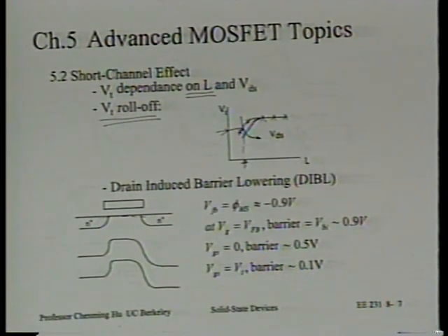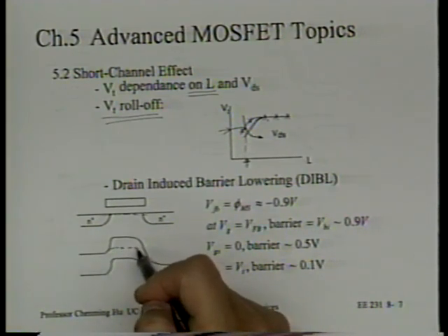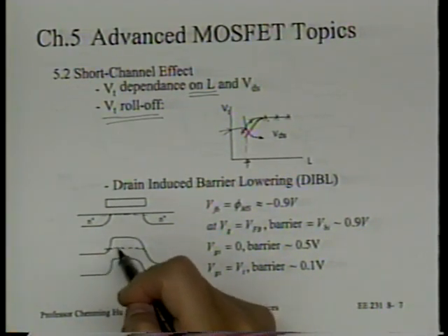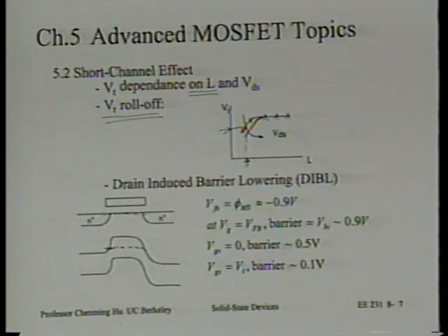Now finally, when VG is equal to VT, what is the barrier height? Okay, a good concept is when VG is equal to VT, NS is equal to 10 to the 17th. We used the number last time, right? As a new definition of VT, right? And in that case, the barrier height is 0.15 volt, all right? So it's good to think this is the picture at VT. Okay, 0.15 volt barrier. Are we okay?